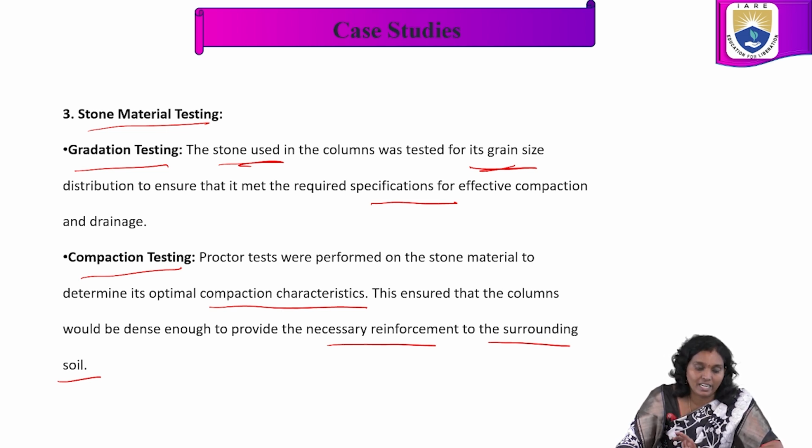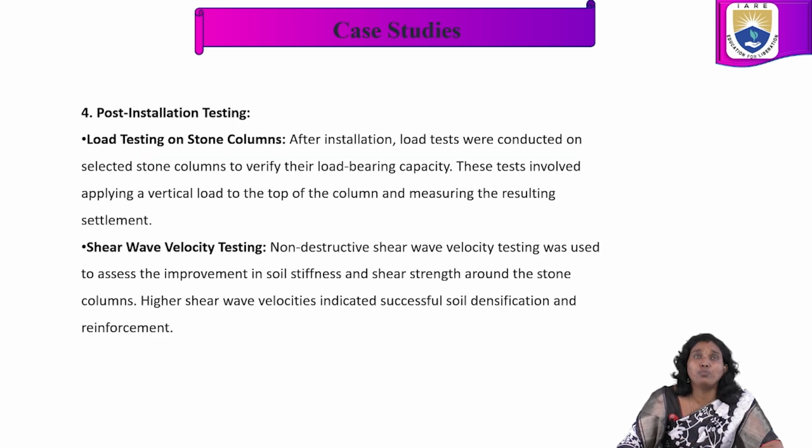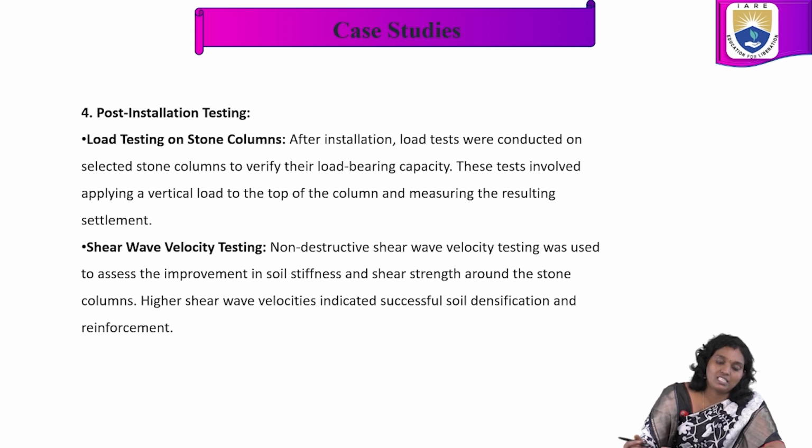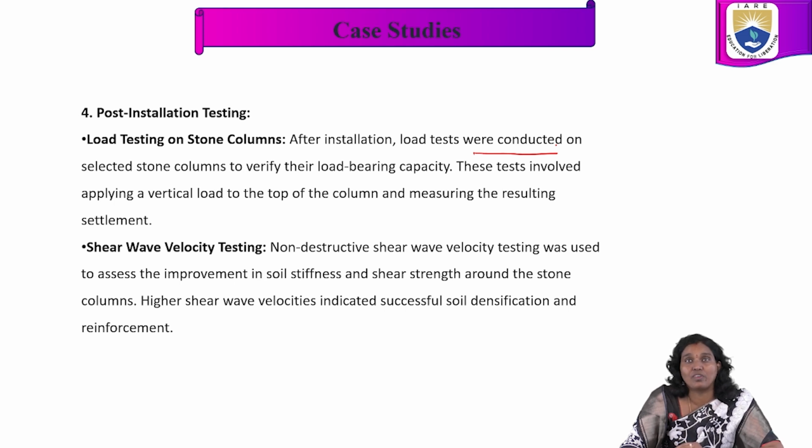So here we are conducting this gradation test for understanding the effectiveness of the compaction and the drainage. This compaction test ensures the columns provide the necessary reinforcement. Now, post installation testing. So here, load testing on stone columns. After installation, load tests were conducted on the selected stone columns to verify their load bearing capacity.